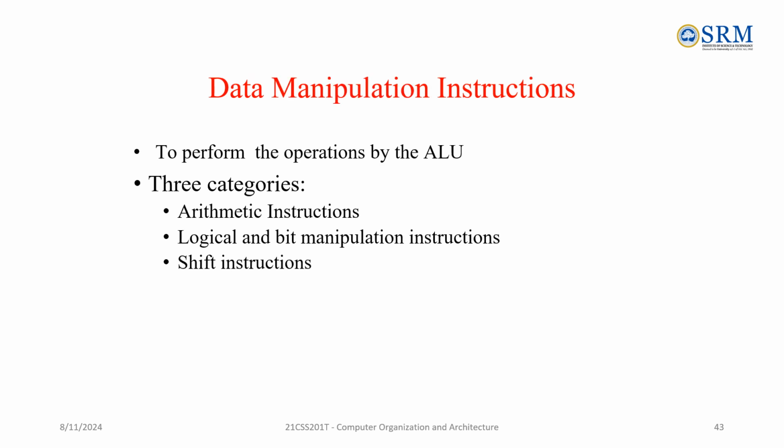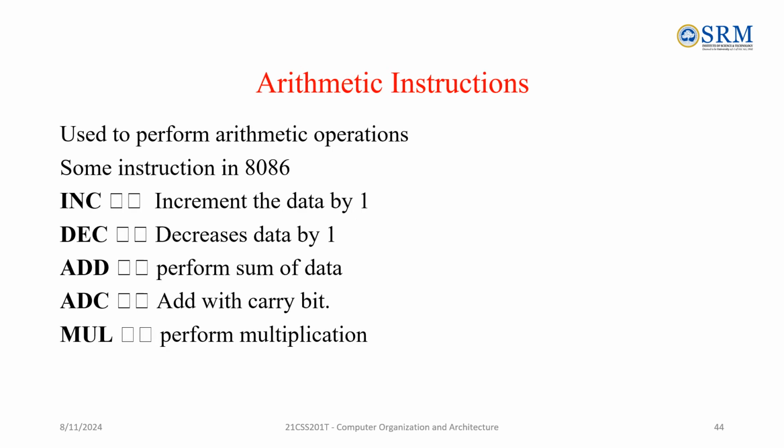Next is data manipulation instructions. There are three categories: arithmetic instruction, logical and bit manipulation instruction, and shift instructions. So arithmetic instructions are INC, DEC, ADD, ADDC, and MUL. INC is nothing but increment the data by one. DEC is decrement the data by one. ADD is perform sum of data. ADDC is add with carry bit, and MUL is perform multiplication.